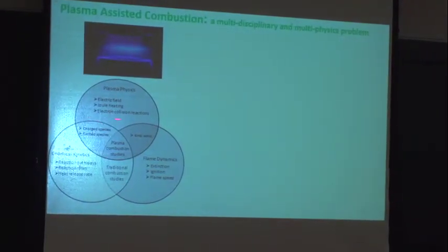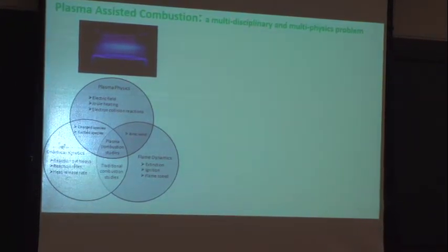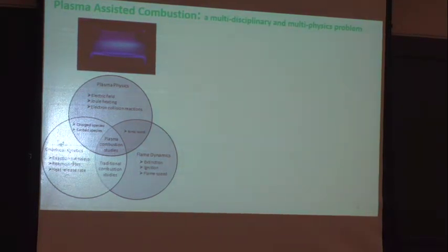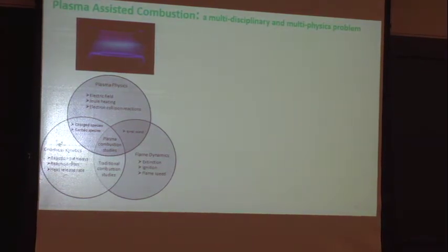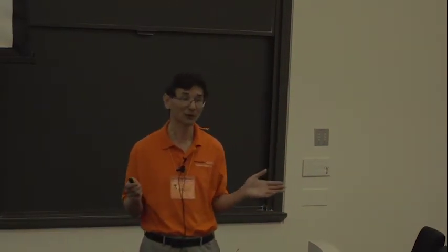And then they initiate the electron collisional reactions, because as I said, the very energetic electrons can initiate reactions very fast. For example, in hydrogen ignition, if you heat the hydrogen in a shock tube to, let's say, 1,000 Kelvin and wait for ignition to happen, it probably takes about 50 milliseconds, right? So the 50 milliseconds is really limited by what? Limited by the first radicals to be produced, right? Because for hydrogen, the reaction kinetics is very fast, but the mixture is hungry for initial radicals, right?